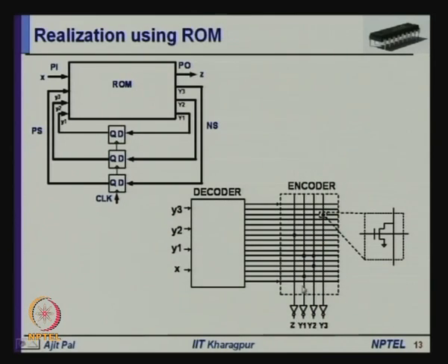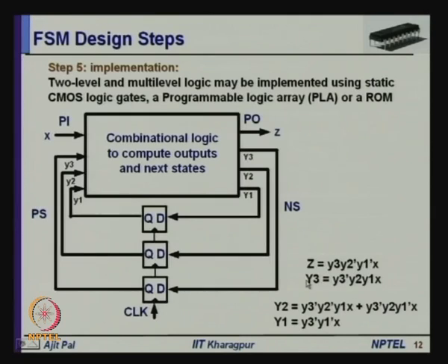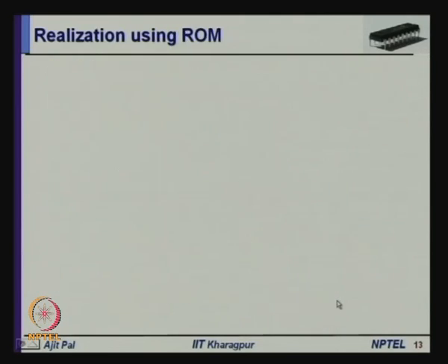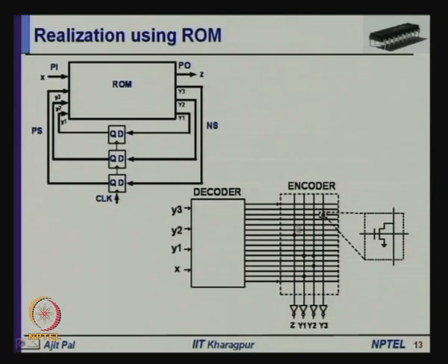So, we have seen there are 5 terms in the function. Actually this has to be expanded, because in capital Y1 I have combined 2 minterms to get this minimized form. So, there are 6 terms. Essentially it has 6 minterms to realize the functions, and those 6 minterms are shown here with the help of 6 dots.